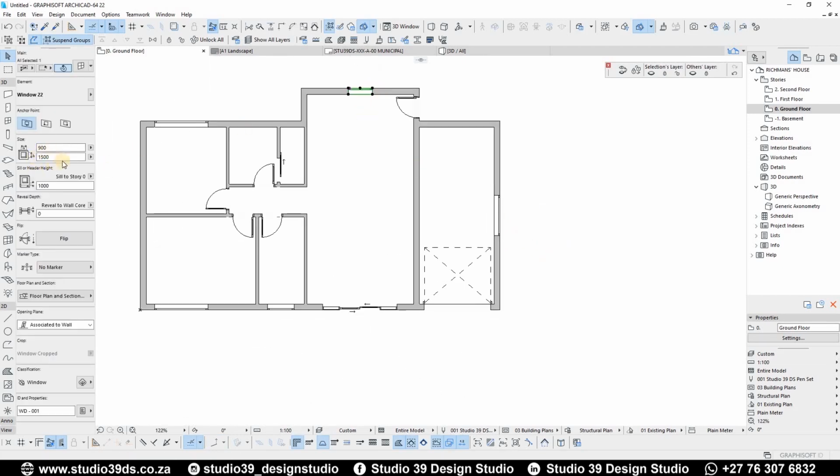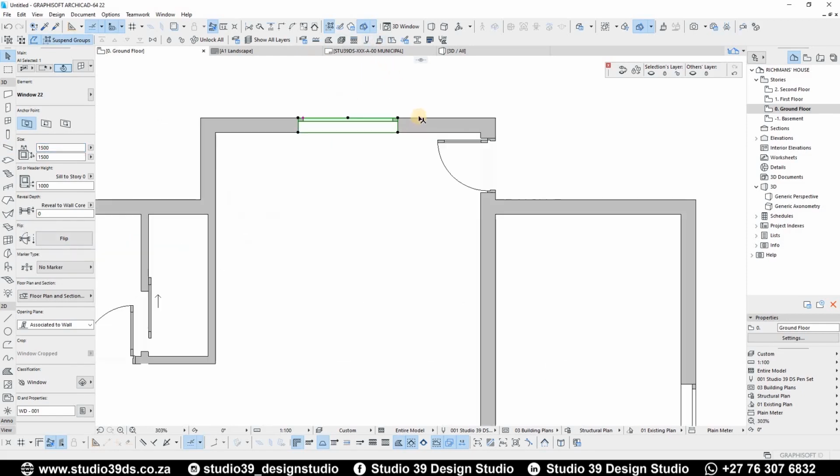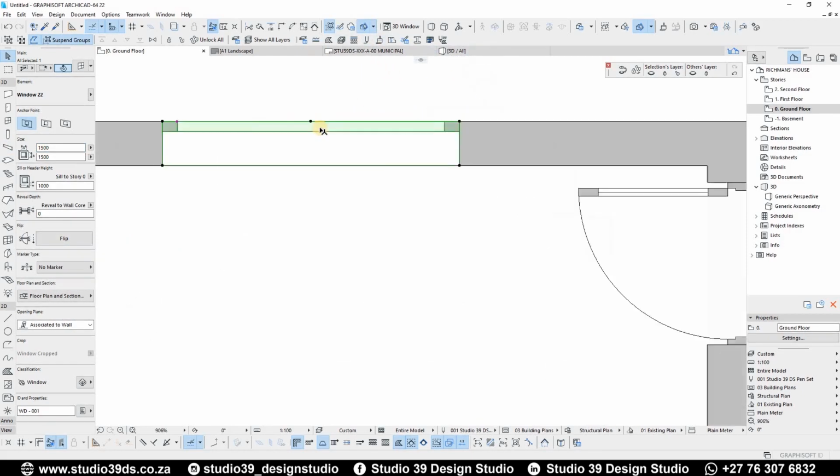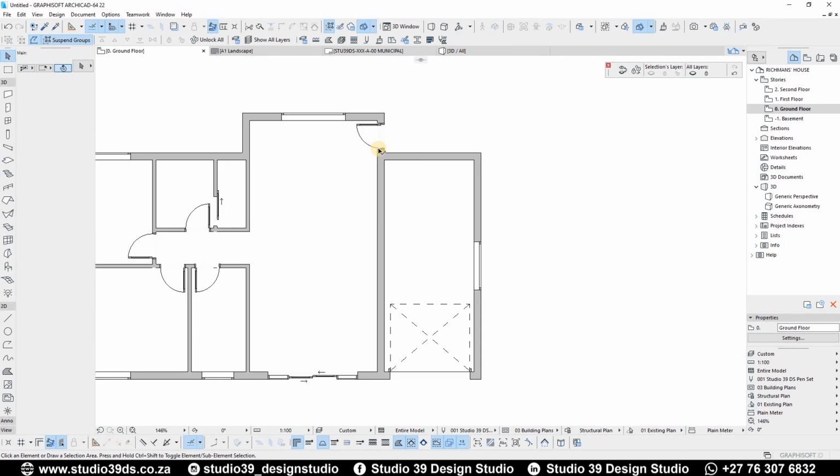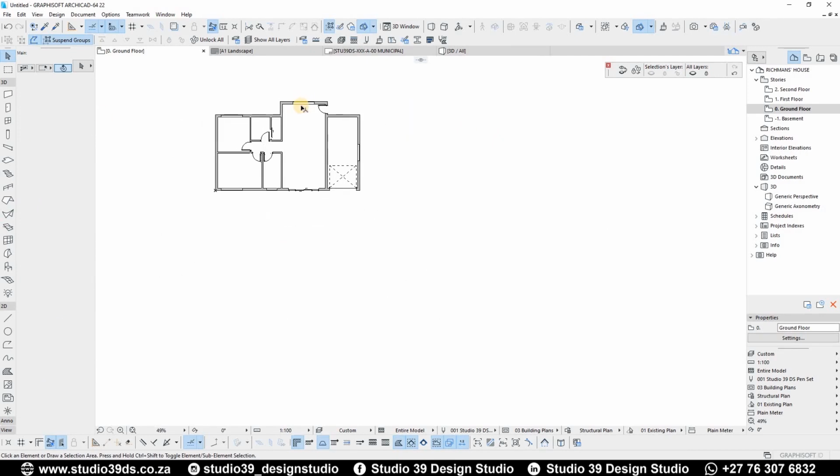And this one, let's have it at 1.5 also. So let's go ahead and say 1.5 meters, right? And then I'm just gonna hover over the wall to see where the center is, and it's right on the center, right on the money right there. I could go ahead and make this 2 meters. Let me just see. That's fine. I don't think that's too extensive, right? So we have the doors, and then we have the windows. What's next? Furniture pieces.